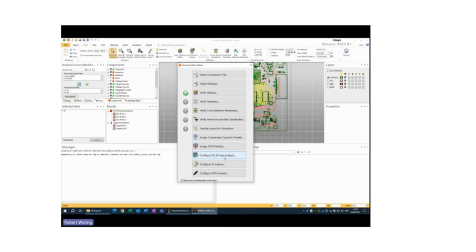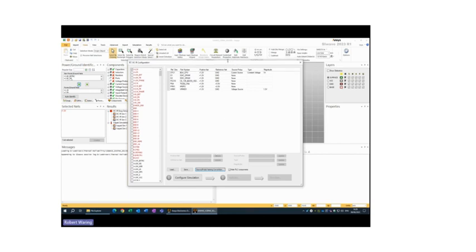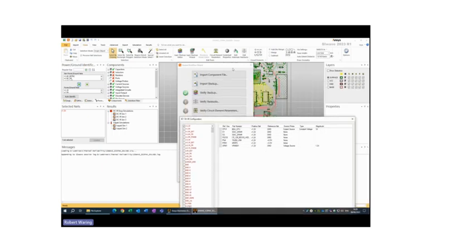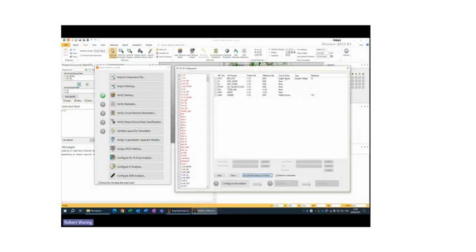To do a thermal analysis, we need some electrical losses to act as sources for our thermal energy. Otherwise, if that didn't happen, we wouldn't have a problem. So we're going to look at the power plane between this VRM and this integrated circuit here, this CPU. We apply a voltage source here, 1.2 volts, and a current source to the CPU, then we configure the simulation, validate, and simulate.